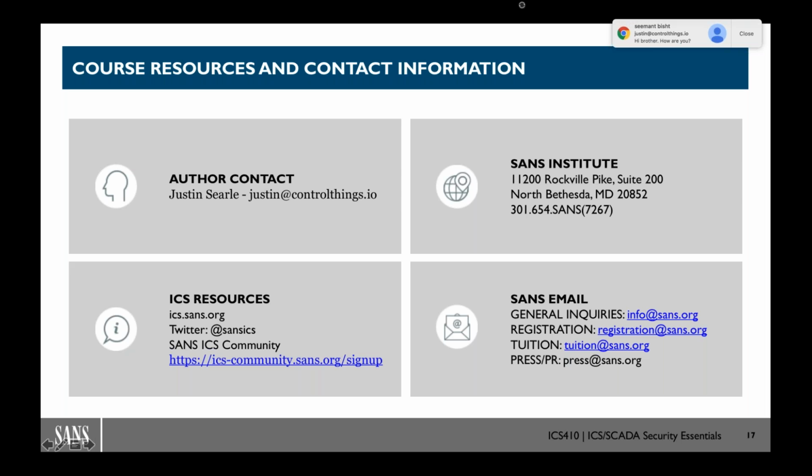The biggest difference is you want to make sure you do a unique deployment of Active Directory at that plant. So it would be a separate Active Directory server with a separate domain that has absolutely no trust relationship back to the enterprise. So you can have role-based access and centralized authentication, just make sure it's not connected to the enterprise, because we don't want any compromise of the enterprise AD from spreading or being used as a mechanism to get into the control network.